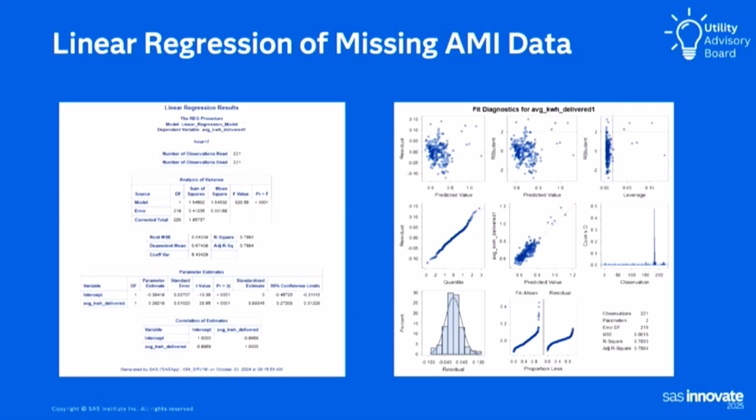Okay, sorry. The objective of this analysis was to estimate missing 1 hour interval data from missing or faulty communication AMI meters, using data from operational meters in a specific area of Los Angeles. So our goal was to create a complete 24-hour load profile. To do this, we applied group linear regression hour by hour over a 1-year period.